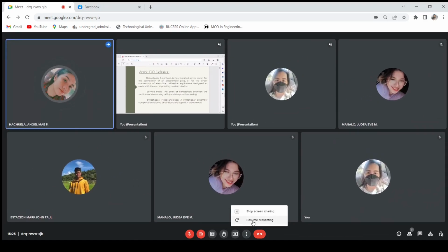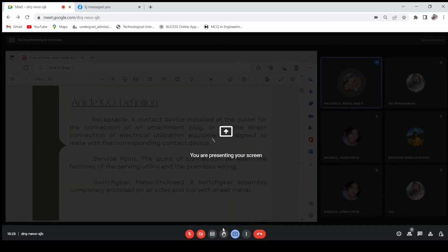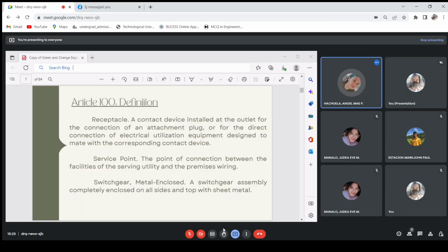So, what sets metal clad apart from metal enclosed is that all of the internal components are also individually clad in metal or compartmentalized. Each of these components may also be insulated, as in the case of bus bars, and grounded individually, and the different compartments can be removed individually as well with a minimal effect on the overall system.